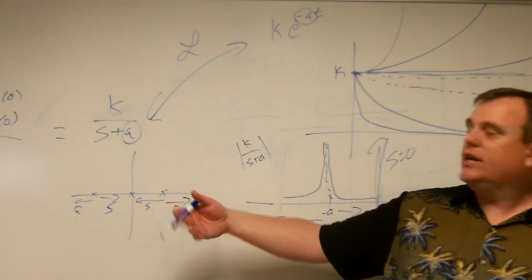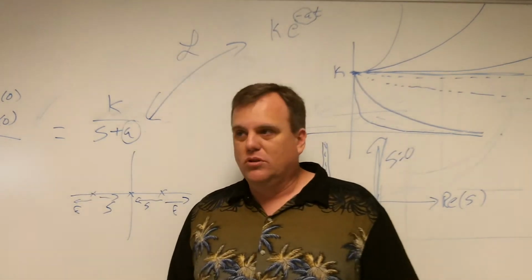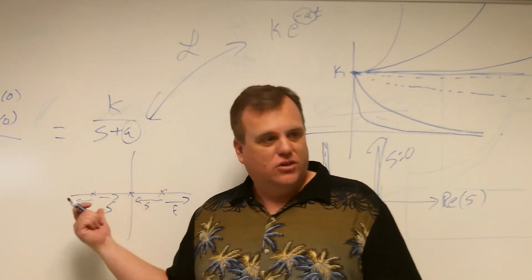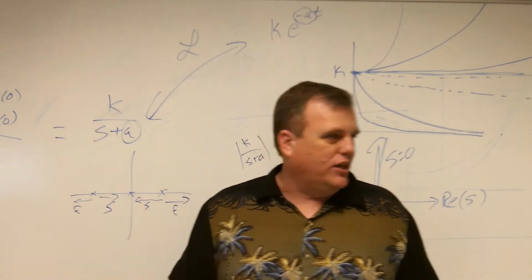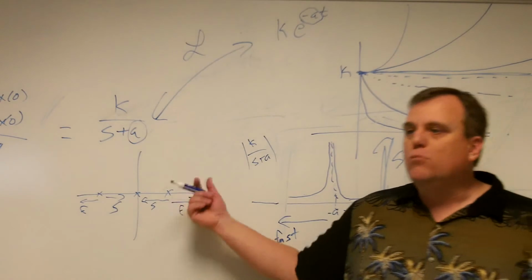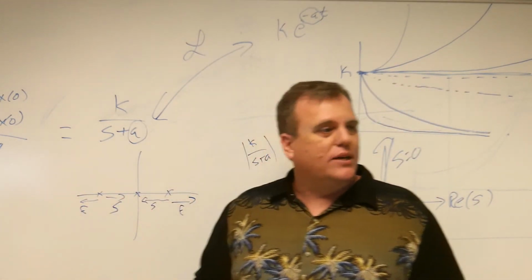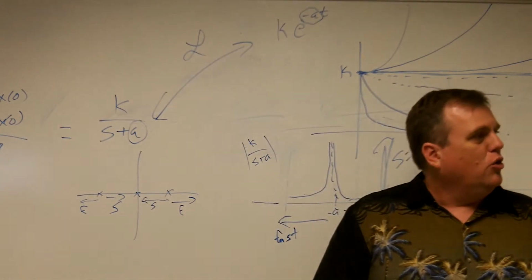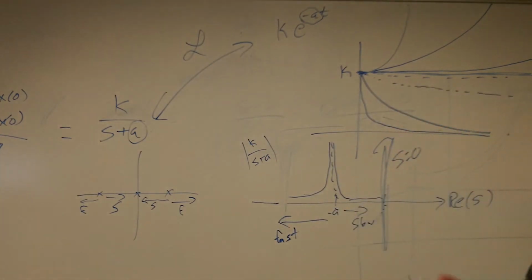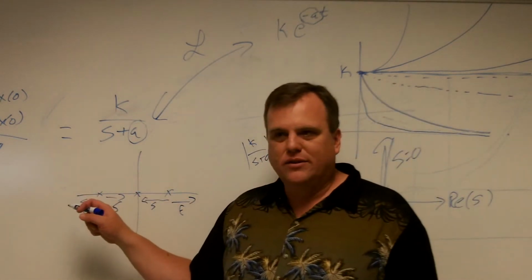So now you can just look at a plot of your S domain and tell stable or not stable. Anything on the right-hand side that are X's, it's out of there. It is unstable, and we will have to do something to move those poles over to the left half of the plane. This is the big thing that goes on with control: if you want me to get someplace faster, it means the transients have to go away quicker. So what are you going to want me to do? Decay faster. You don't want me to shove the poles more that way.